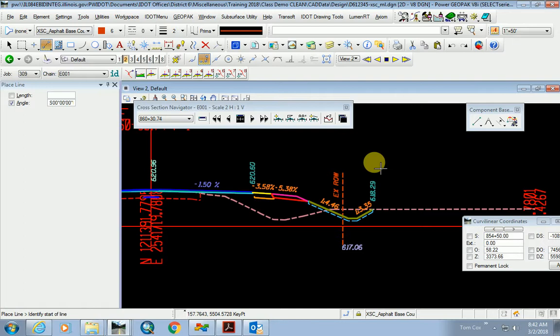Because in this district, that's the way Land Act operates. They may tweak it, but they want us to take a stab at how much right-of-way you need. Because you're not just going to follow the construction limit. You're going to come up with something that includes the construction limits, but is at some nice even station and probably a nice offset, and it's a straight line, that sort of thing.